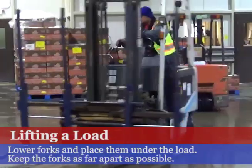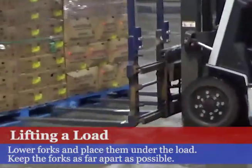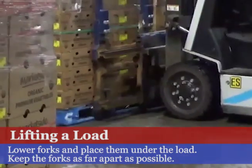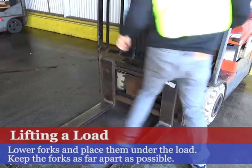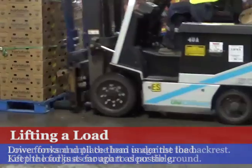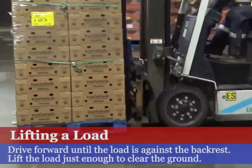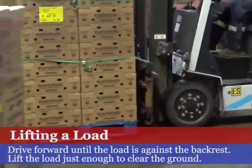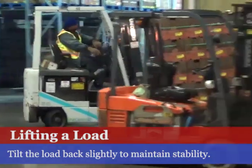After you verify the load is stable and is within the vehicle capacity, lower the forks, and place them under the load. The forks should be as far apart as possible, to help stabilize the load. Drive forward slowly, until the load is resting against the backrest. Lift the load just enough to clear the ground. Use the tilt control to tip it back slightly for stability.